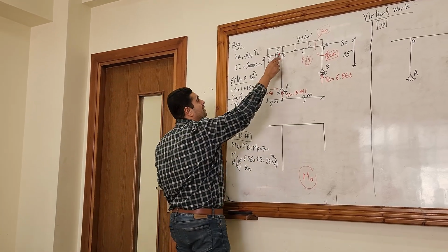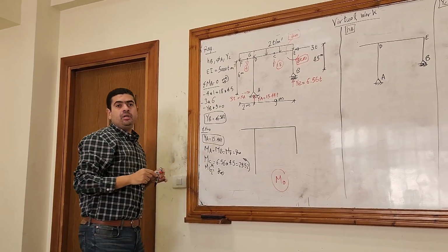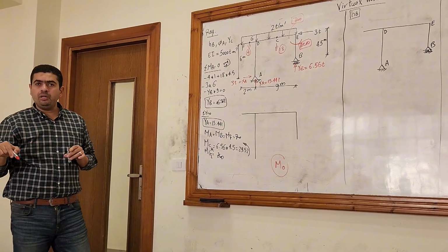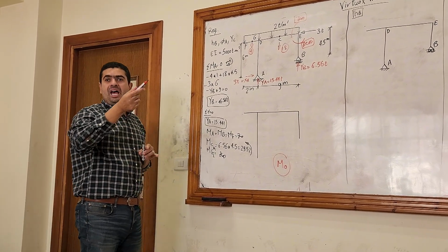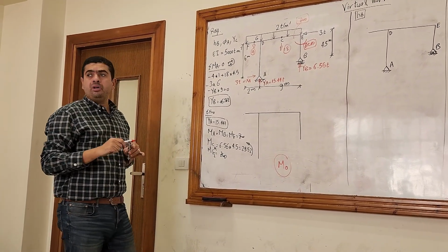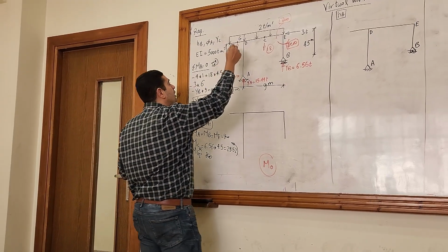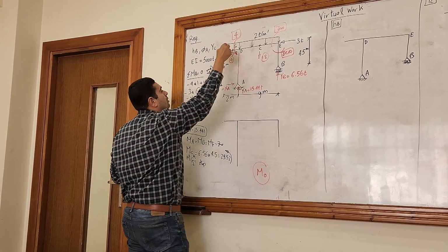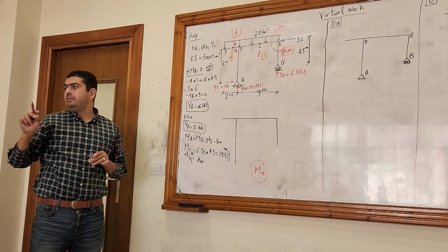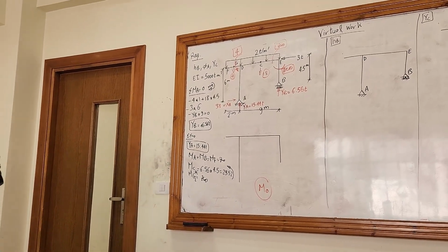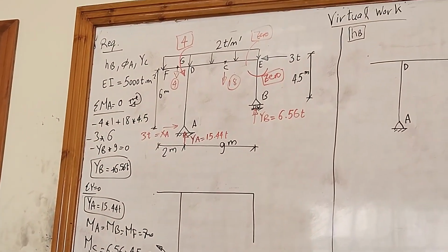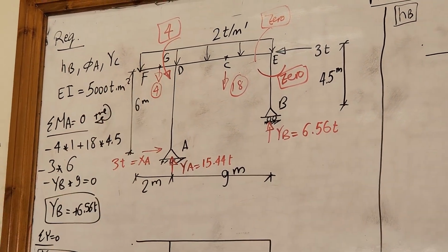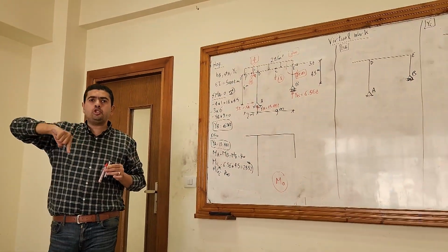What is the moment at D from DF? It's only 4 multiplied by the distance 1. So it's 4, and it's anti-clockwise. Look how I put the moment on the joint. It will be like this. So I put the moment on the member that I calculate the moment from. I calculated the moment from the member DF, so I have to put the moment on the member DF. And it's rotating around the joint.